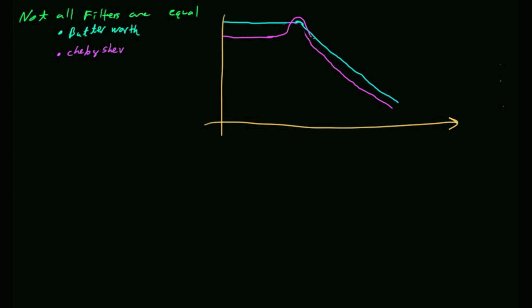But I said if you were capable of tolerating those differences in passband behavior, then you can get much better performance in the stop band for the same filter order, right? We said for a third order function, one of them performs much better than the other one. That was what I was trying to demonstrate. And there's always software tools, you don't actually have to learn any of these equations. If you want to build a third order Chebyshev with a cutoff frequency at 1,000 hertz, boom, it'll just tell you where your poles are.